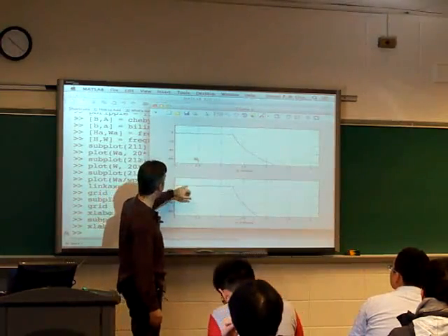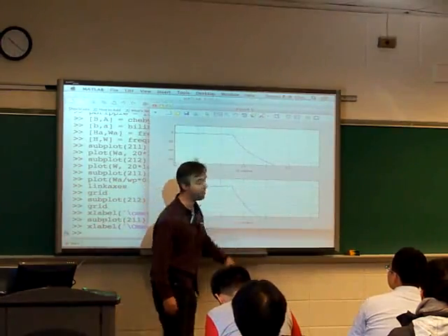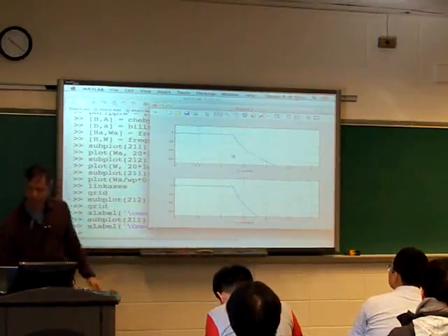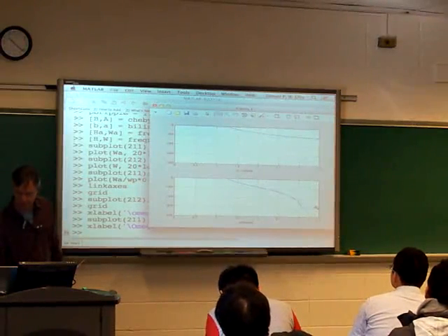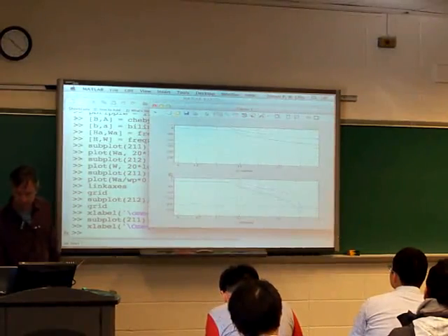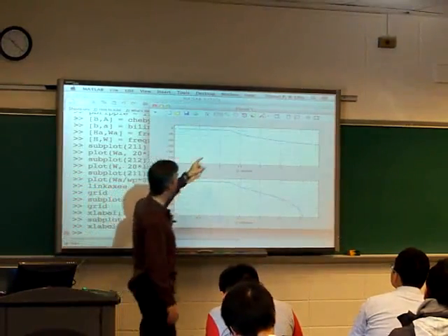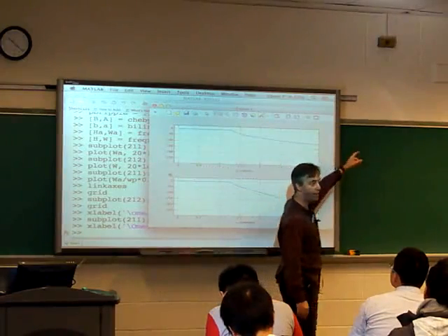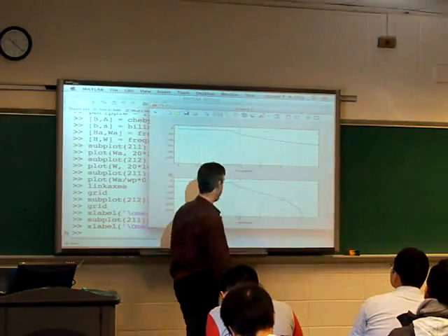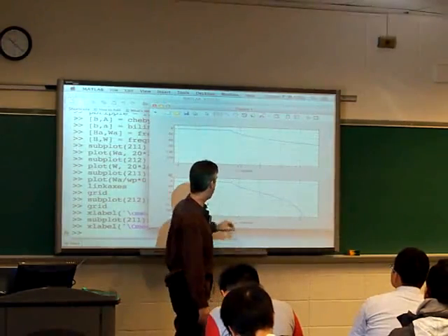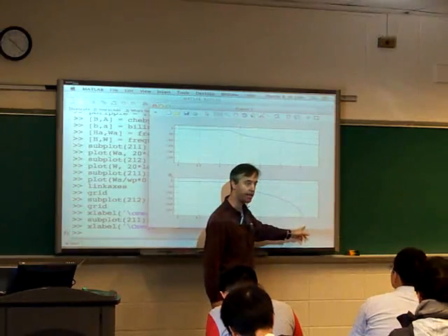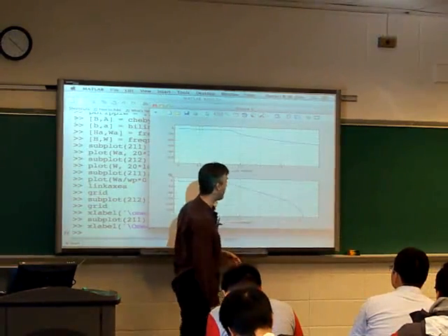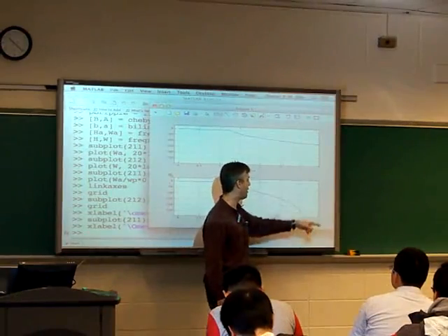And they look pretty similar. We've got some ripples here, and we've got some slope here. But if I zoom out somewhat, like this, we see the difference now in how this slope falls off here. This is from 0 to pi radians per sample. And so this is the asymptote of the frequency axis in discrete time. After this it starts repeating.